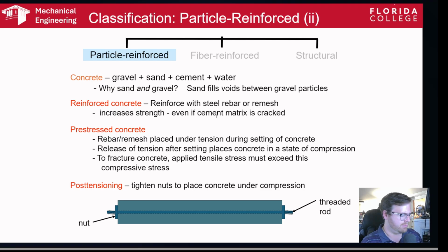So the thing about cement, well, really ceramics in general, but also the thing about concrete is it's much weaker under tension than it is in compression. You can put a lot of weight on it in compression, but if you try and pull on it, it'll break quite easily because it's so brittle.